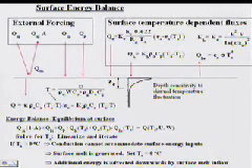If the energy content is less than that, the temperature will be below the freezing point, and the amount it's below the freezing point is based on the heat capacity of the snow, the water equivalent times the heat capacity of snow times its density, as well as the ground below that's also involved with the snow. So we are thinking here of an average temperature of the entire snowpack and some ground below that.